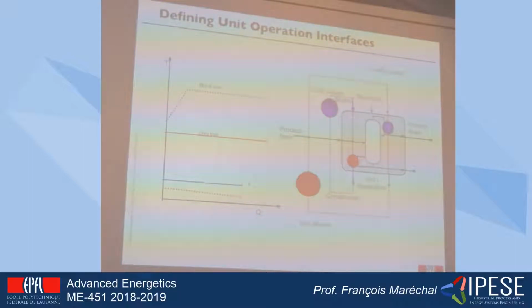If now I want to do the same operation but going into the details, then I can even go inside the system. So I realize that in the distillation column, the flow could be preheated first, and that the heat transfer can be not only done by the condensation here and the evaporation here, but can be distributed over the whole column, which gives a profile like this one here, with streams to be heated and streams to be cooled down.